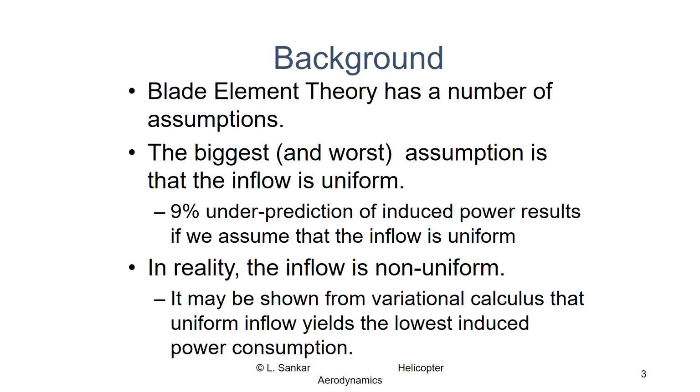Then we will also use a theory called variational calculus and show you that a uniform inflow is the best because it will produce the lowest induced power, therefore the lowest total power in many cases. So when you design a helicopter, you do try to make the inflow as uniform as possible, because instead of a kappa equal to 1.15, you want to make kappa smaller than that. It's like 1.06, 1.07. By making the inflow uniform, then you get a better design or a better rotor. So we will cover that a little bit later in this set of slides in this video recording.